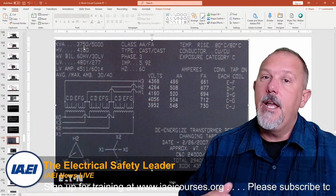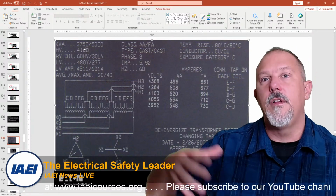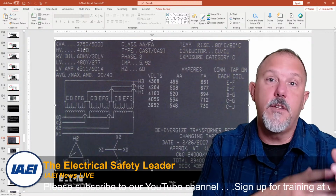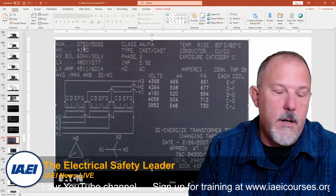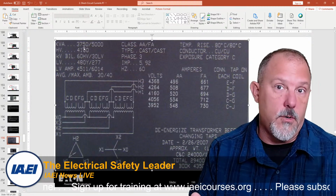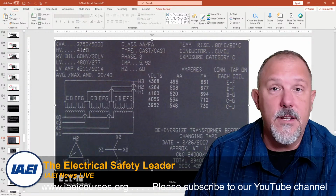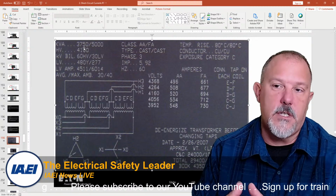With regard to the transformer, we're looking at the short circuit impedance through that transformer, what impedance it provides to the system. Fans aren't going to make a difference. The fans are there to cool it over a time period to get more kVA out of it, but it doesn't change the physics of the transformer itself, because we're looking at what? A cycle. And when we do our calculations, we're looking at a quarter cycle or the first half cycle, right? And that's where you get the most impedance. And whether or not I have fans on it doesn't make a difference. I'm not changing the physics of that.